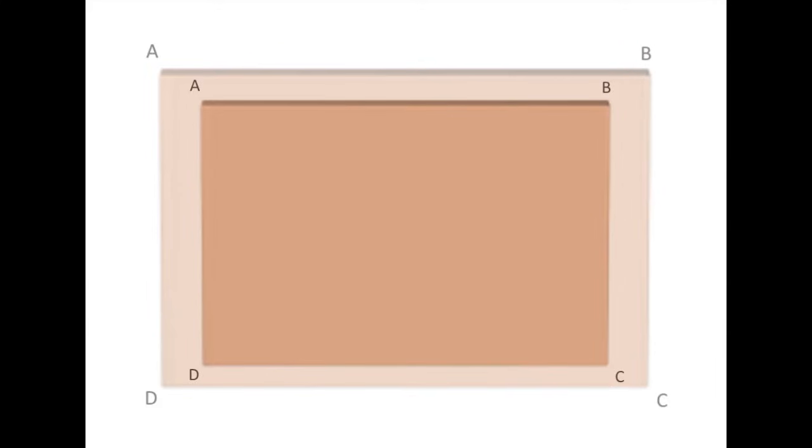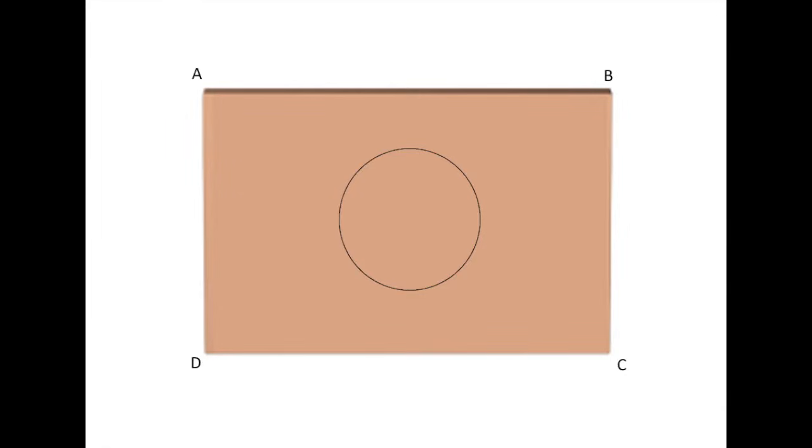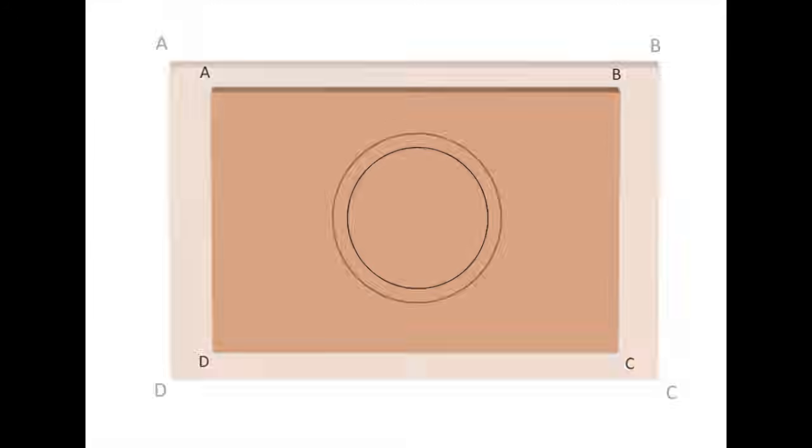Okay, now let me consider this case and put one circle with the same material within that hole. We just disconnect between the circumference of that circle and the plate. What happened in this case? What if I increase the temperature? Do you expect that the disk gets larger and the plate gets larger as well? If I increase the temperature, there is not any internal stress. So the entire element is stress-free.